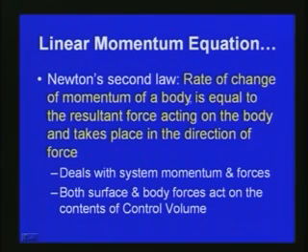Using this, we can see that it deals with system momentum and forces. If we consider an open system or a closed system, Newton's second law deals with the momentum occurring with respect to the control volume, or between the sections which we consider, and the forces acting on the control volume.